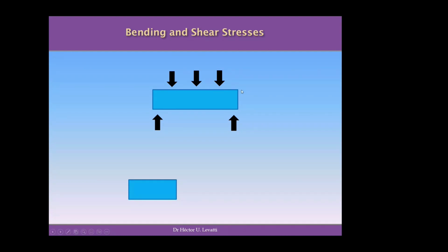And when you apply these forces and you have these restrictions in here and you produce these reactions, the deformation you expect to have, and you can see it easily in a test, or because you have studied the simply supported beam before, you expect the beam to bend in the way that the figure shows on the screen. So you see now that this beam as well has an infinite number of cross sections.